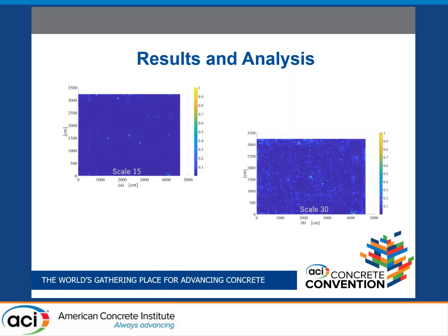And this kind of makes sense. Everything else is pretty much at the same height, and in the previous depth map we saw that the slab is relatively flat with a few little peaks. In fact, the average value of the deviation in the z-axis height was 0 centimeters with a standard deviation of 0.3 centimeters.